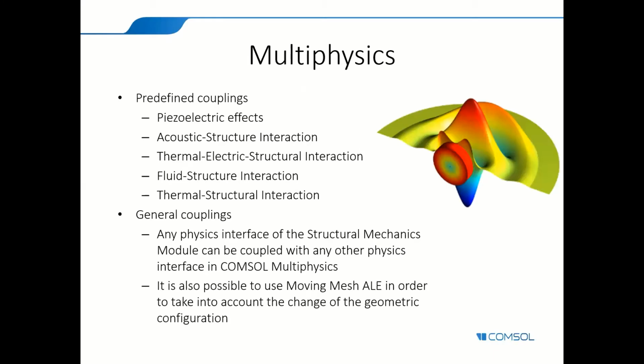As I've said, you can find lots of multiphysics between structural mechanics and other modules, such as the piezoelectric effect by combining the AC/DC module or electrical currents and structural mechanics. You can simulate the effect of an electrical current or electrical field on a piezoelectric material both ways. For example, you can apply a potential difference across a certain material and see how it deforms and what stresses arise. Or the other way, you can apply a certain pressure or stress upon a piezoelectric material and see what kind of electrical field develops in the material.